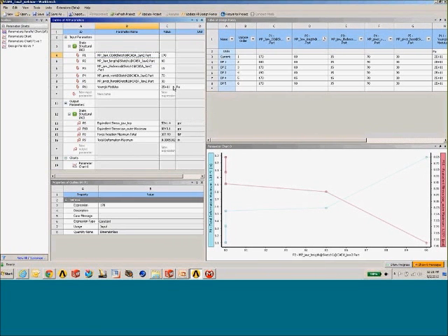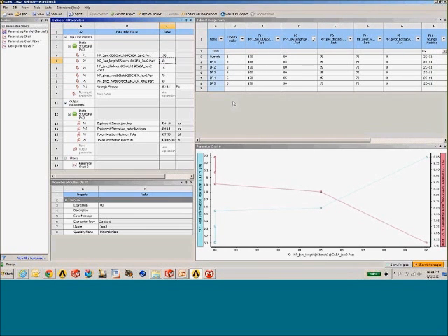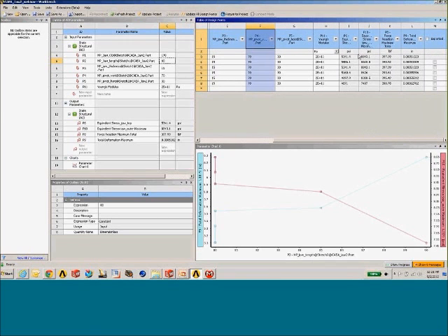So if I need to regenerate a single design point, I can freely go in and edit the value of the input parameter here. These are all open boxes that I can change. But I may also want to look at a table of design points. So over here in the upper right-hand column, we'll see a table. We'll have our input quantities listed as the first columns, and that will be followed by the output quantities listed as well in this table.